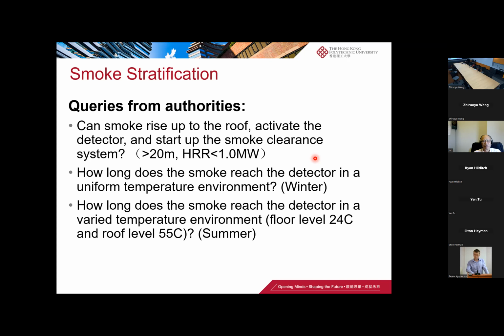This is a very restrictive requirement because in Beijing and Shanghai airports, we basically designed the circulation area fire heat release rate as 5 megawatts. This is because the airport needs to place some commercial areas like kiosks of about 9 square meters. But with 1 megawatt, you cannot put any commercial activities in the airport.